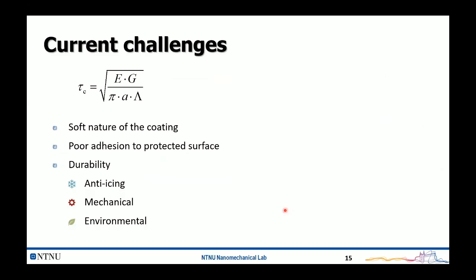So far, this mechanism we proposed for low adhesion has been very successful, and we got a lot of attention from the field. However, we are also facing some challenges. We are using this fracture mechanics-based model to reduce adhesion by maximizing the deformation incompatibility. But at the same time, it's basically just a soft material. So we have the problem of the low cohesion strength of the surface.